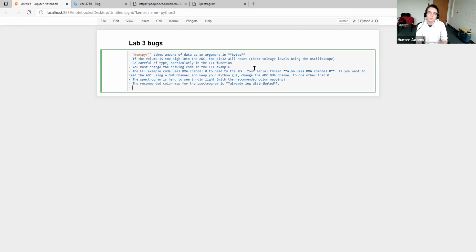You may find, in fact you almost certainly will find, that there is a DC offset to the input to the ADC, and the result of that in your spectrogram is a horizontal line at 0 hertz. That is the DC component of the input signal, which we aren't really interested in. So if you're not careful about this and you compute the max frequency, what you'll likely get is that the frequency with max amplitude will always be 0 hertz. And you'll go, what the hell's going on? I'm using this tone generator, I'm putting in 400 hertz, whatever it may be, and it's always 0 hertz. It's because there's a DC offset. So if your max frequency calculations do not include the bottommost bin, the bottommost index of the output array, or perhaps even the bottom few bins, then the output max frequency will be what you expect it to be.